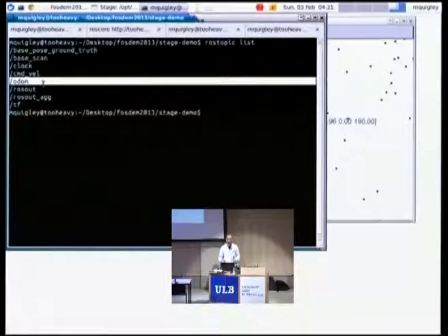So odometry in a robot is when every time the wheel turns, it keeps track. There's usually a piece of hardware in a robot that counts how many ticks the wheels have turned. And so if you make assumptions such as the wheels don't slip and the tires are the same size, you can then integrate that and get a position estimate.